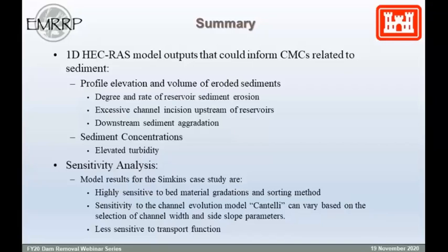And so I learned that with the 1D model, I was able to see how my profile elevation changed over time. I was able to see areas downstream that experienced aggradation, and then throughout time that aggradation, in this particular case, was temporary. And I was able to see how the incision channel progressed upstream, just comparing model results with observed data.